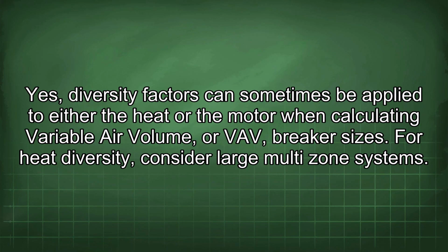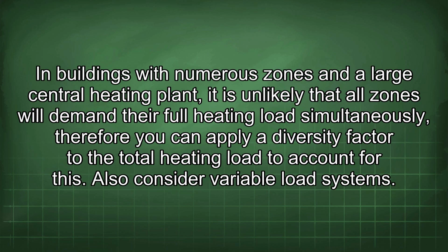Yes, diversity factors can sometimes be applied to either the heat or the motor when calculating variable air volume, or VAV, breaker sizes. For heat diversity, consider large multi-zone systems. In buildings with numerous zones and a large central heating plant, it is unlikely that all zones will demand their full heating load simultaneously, therefore you can apply a diversity factor to the total heating load to account for this.